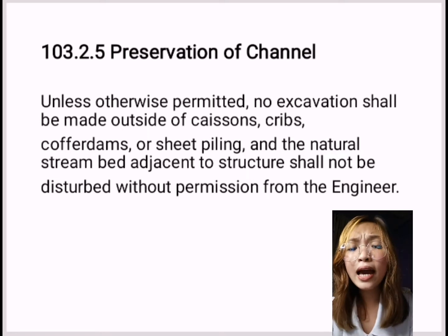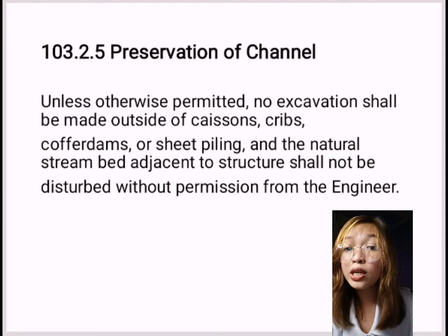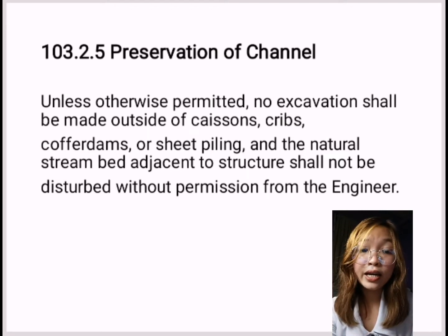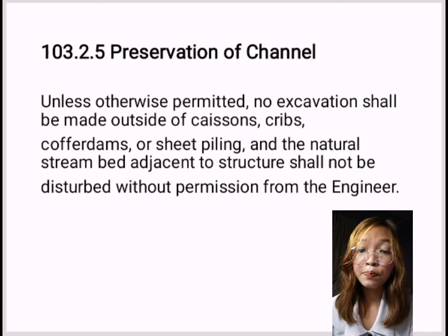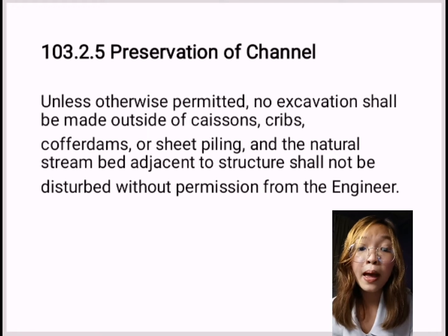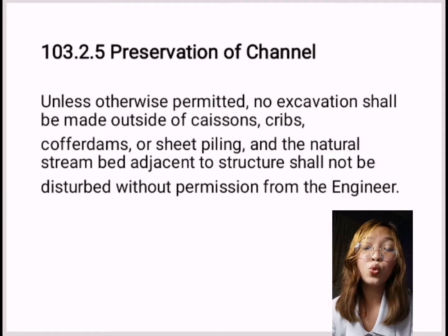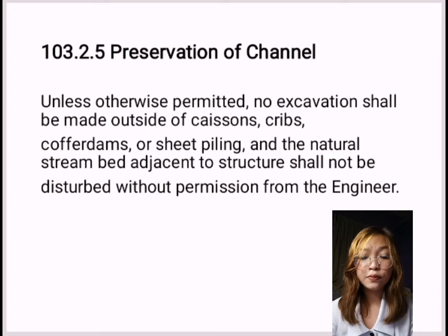So if any excavation or dredging is made at the side of the structure before caissons, cribs, or cofferdams are sunk in place, the contractor shall, after the foundation base is in place, backfill all such excavation to the original ground surface or stream bed with material satisfactory to the engineer.